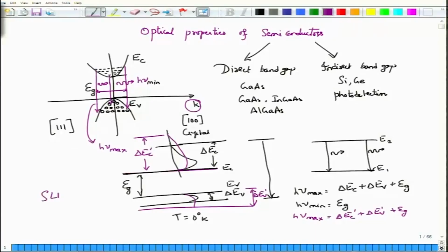Okay. So, in most semiconductor laser diodes, temperature must be maintained very accurately, or with as much accuracy as possible. Temperature must be maintained to a given value. Any increase in the temperature causes the line width to spread, and increased line width is absolutely bad for communication purposes. Okay. So, this is essentially the idea.